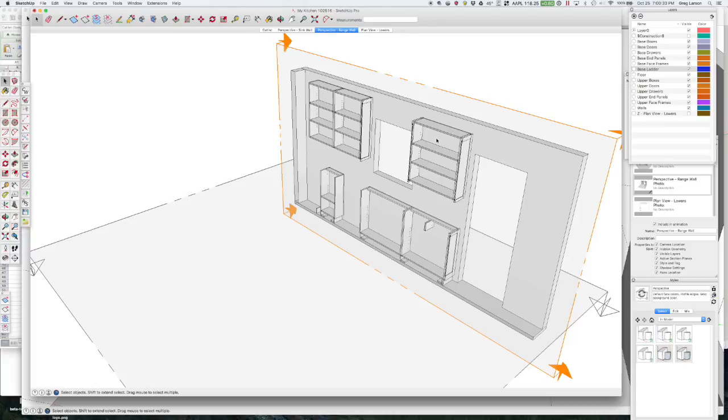What's beautiful about the 3D modeling concept and drawing concept is we're drawing it part by part, so it knows exactly how it's built, which means we can use these built-in sectioning tools in SketchUp to quickly do sections. So once your model is drawn, you can immediately export a cut list, immediately start creating these sections and elevations, and pretty quickly come up with a set of shop drawings.